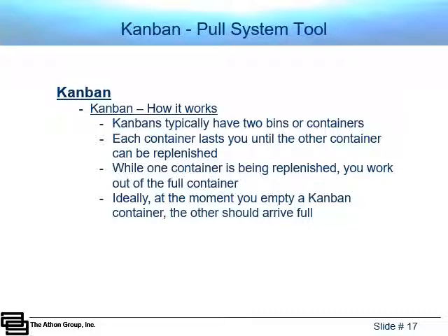So let's say that you use 10 units a day, and it's going to take you a week to replenish it. You start working that project, you've got 2 full Kanban containers. Both of them have 100 units in it. You take that first container and you start working out of it. The first day you use 10, the next day you use 9, the next day you use 11, next day you use 12, next day 8. Eventually you get down to where you have 0.